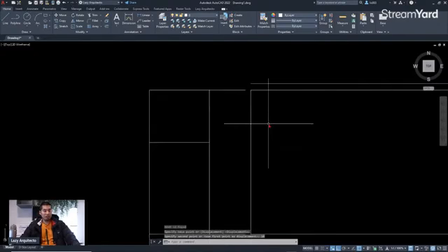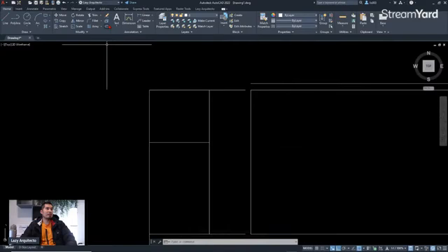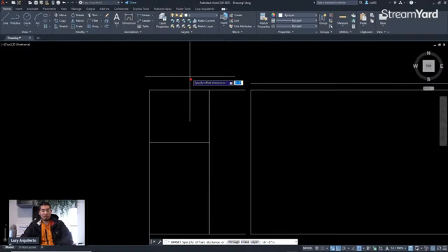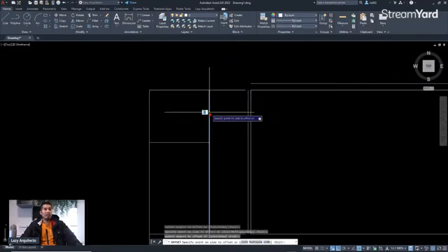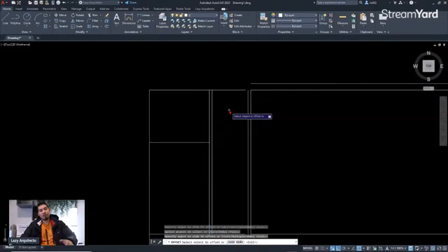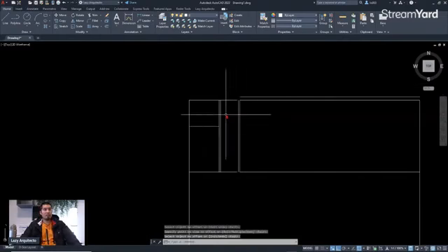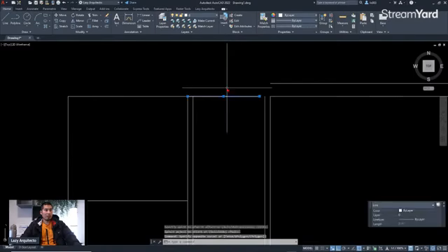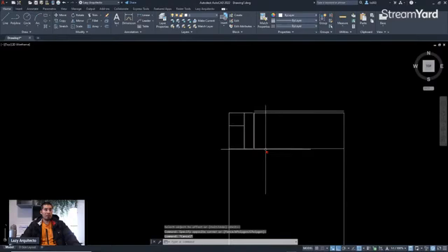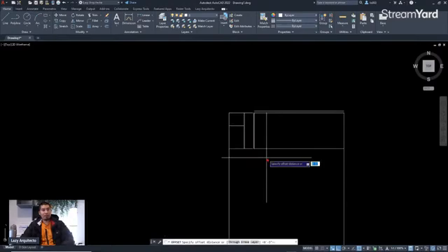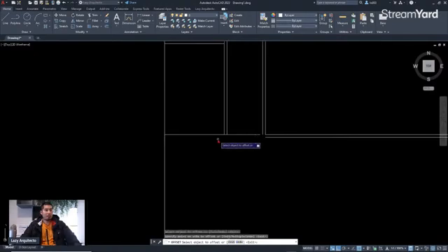Once we do that, we can again use the offset command from the ribbon or using its shortcut. So click 5, enter, and then offset this wall to the left, and again click this other wall to the right to offset those walls. So that's where we want 5 feet 6 to the corridor. Again, we're gonna offset 5 inches these walls down like so.